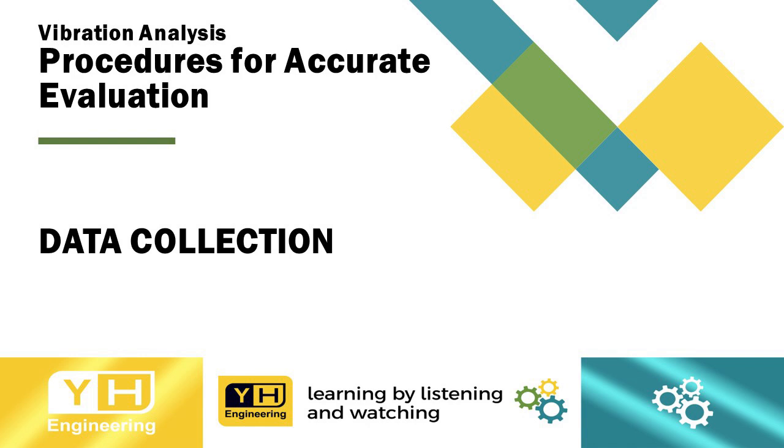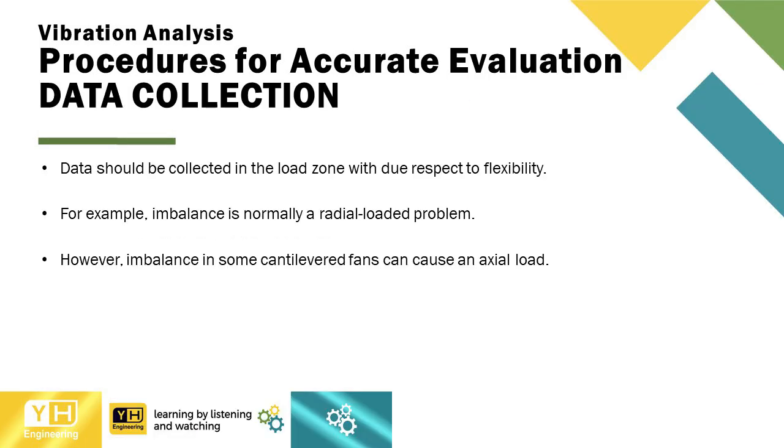Vibration analysis. Procedures for accurate evaluation of machinery condition. Data collection. Data should be collected in the load zone with due respect to flexibility. For example, imbalance is normally a radial loaded problem. However, imbalance in some cantilevered fans can cause an axial load.